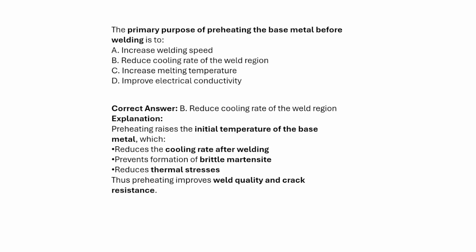The primary purpose of the preheat treatment in base metal before welding is to increase the welding speed, reduce the cooling rate of the weld region, increase the melting temperature, or improve the electrical conductivity. So the answer will be B, reducing the cooling rate of the weld region.